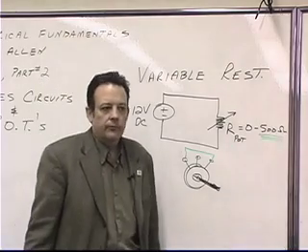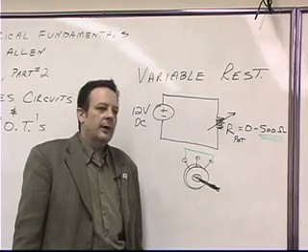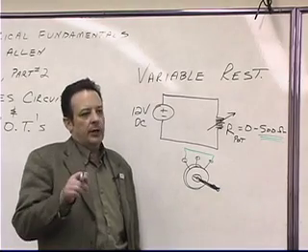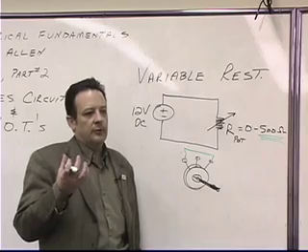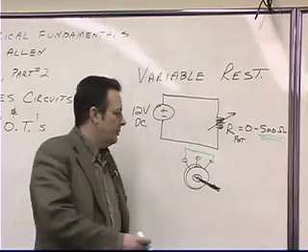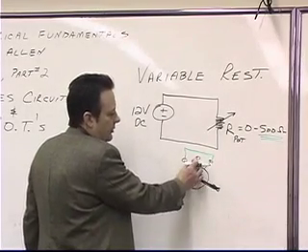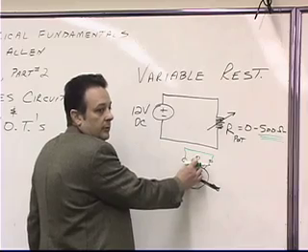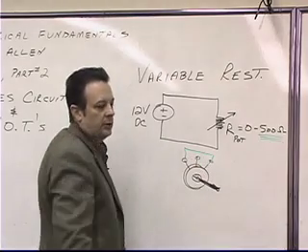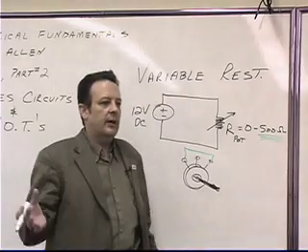Okay. What's up or down? Well, you really have to measure it because it depends on how it's oriented inside the casing of the potentiometer. Some of them, you turn them clockwise and it goes up between these 2 points. And some of them, you turn them clockwise and it goes up between these 2 points. But usually, if you buy a batch of potentiometers, they'll be the same.